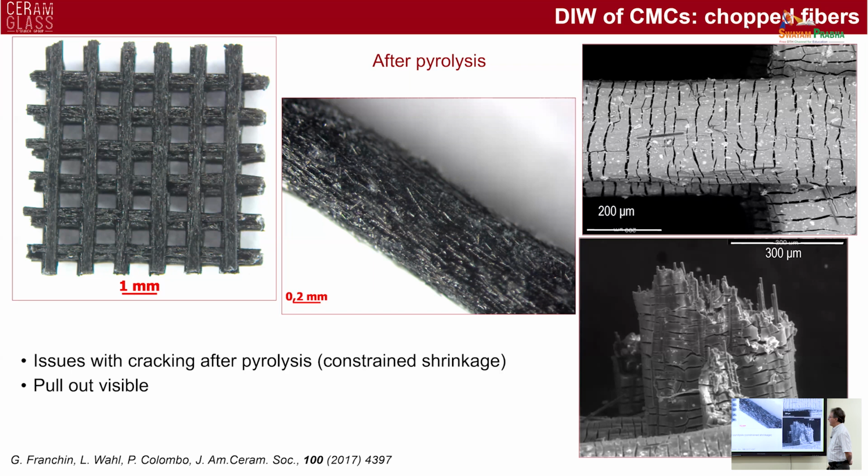So this is initial work, and I forgot to mention that one of the mechanisms in ceramic matrix composites for absorbing energy and therefore increasing the toughness of the composite is the so-called pull-out effect. Basically, short fibers get extracted from the matrix, and this requires additional work rather than simply for the fracture to go through the diameter of the filament.